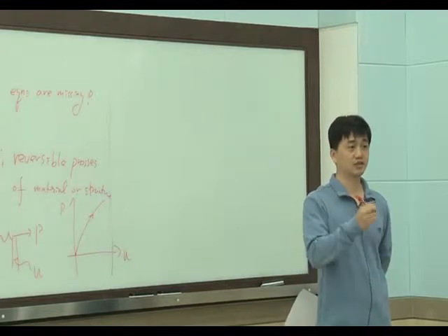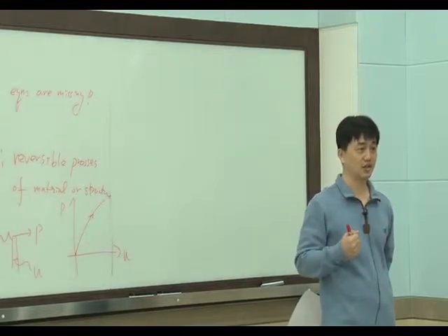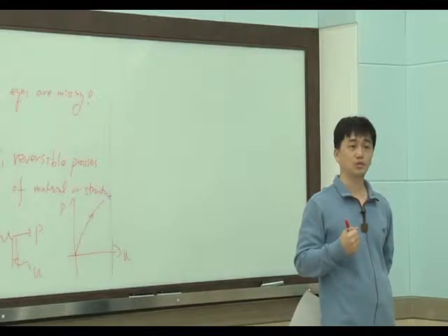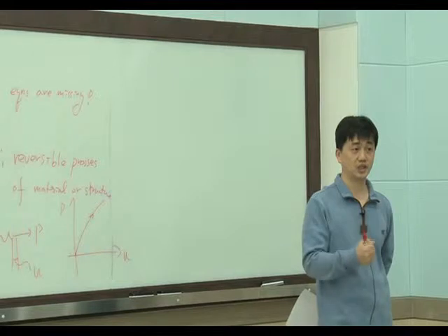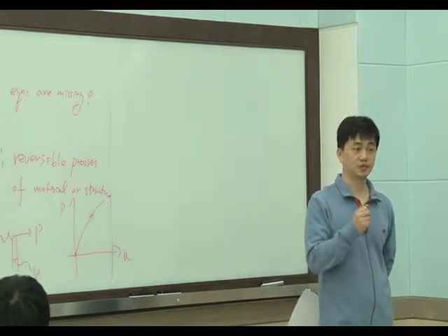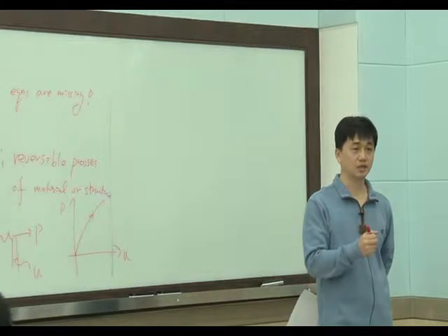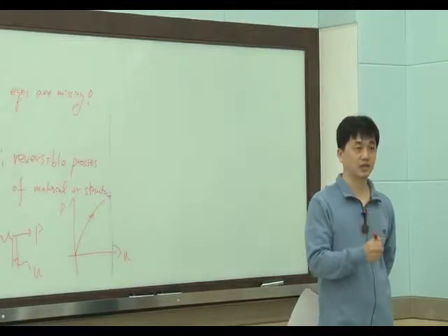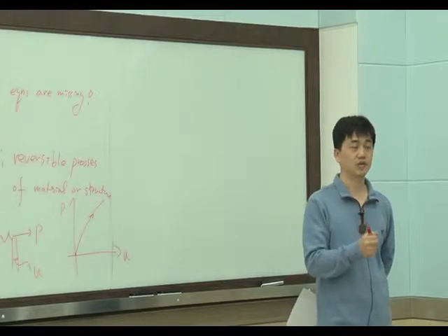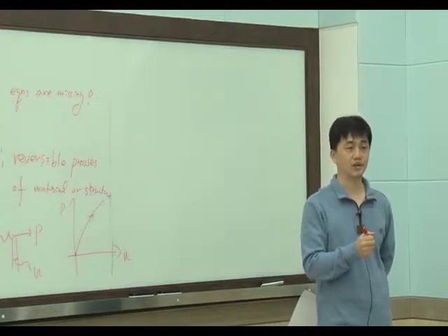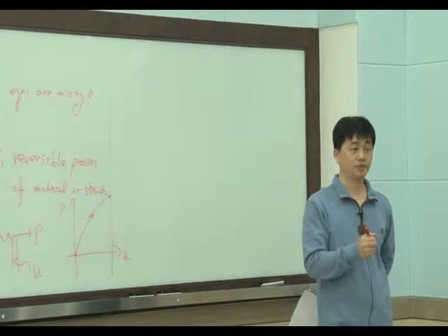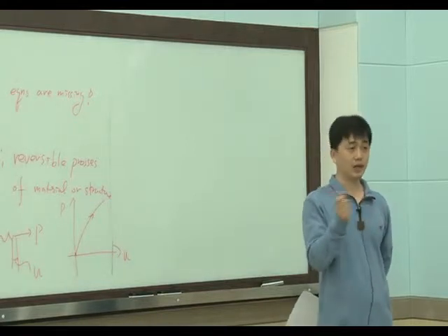If we increase the load very quickly, the loading rate is very important due to inertia. If the loading rate is big, it means there is some acceleration, so inertia forces happen and the structure will vibrate.